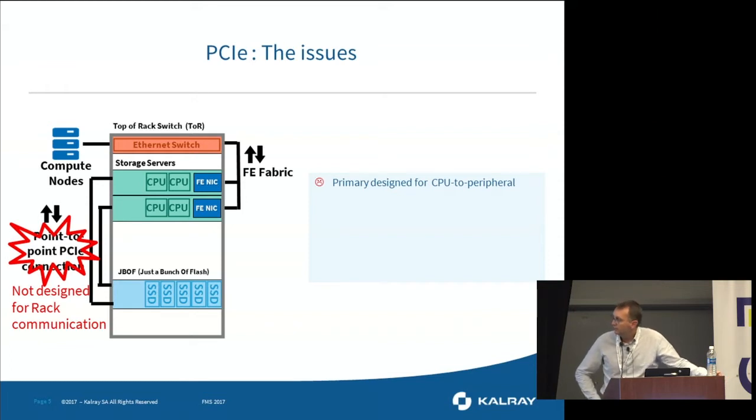And when you are using PCI Express as a connectivity inside the rack, in fact, you see the SSDs as some peripherals, and you are very limited in the number of JBOF that you can connect to your storage head nodes. If I take a concrete example, from what I saw, one existing JBOF can connect up to 6 PCI Express cables. So meaning that you can just connect up to 6 head nodes on this PCI Express JBOF.